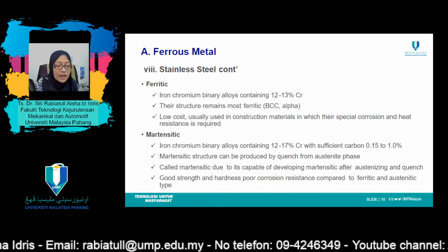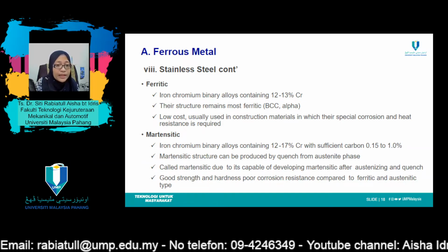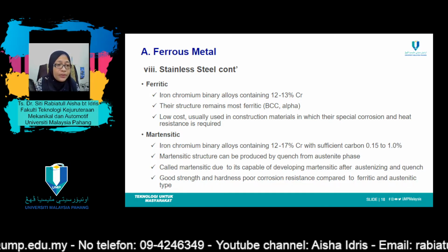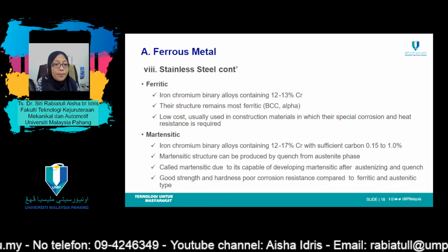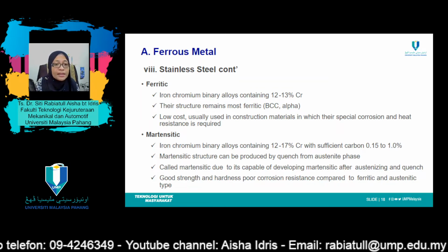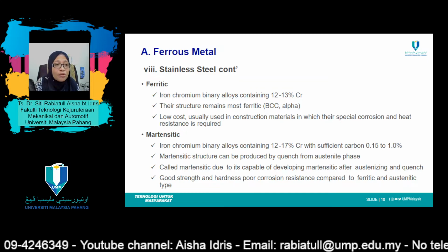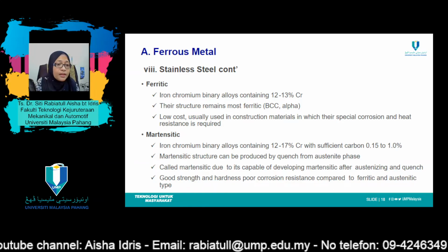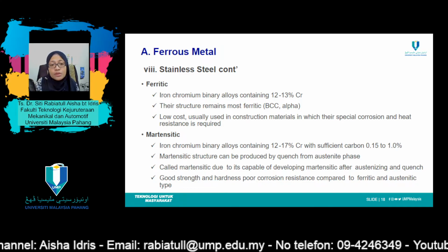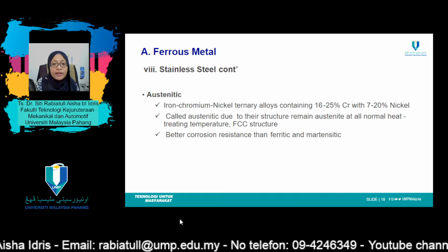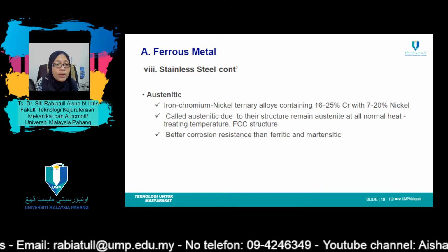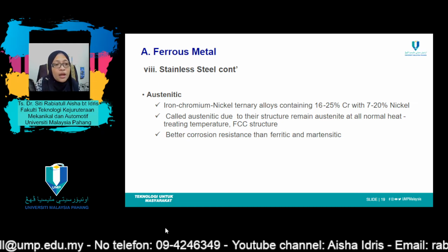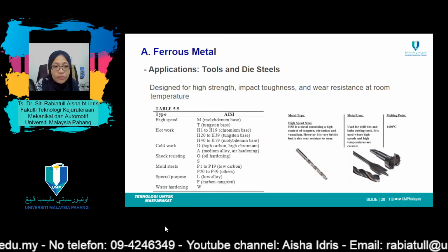Some stainless steels are frequently used at elevated temperatures and in severe environments because they resist oxidation and maintain their mechanical integrity under such conditions. The upper temperature limit in an oxidizing atmosphere is about 1000 degrees C. Equipment employing these steels includes gas turbines, high temperature steam boilers, heat treating furnaces, aircraft, missiles, nuclear power generating units, and so forth.